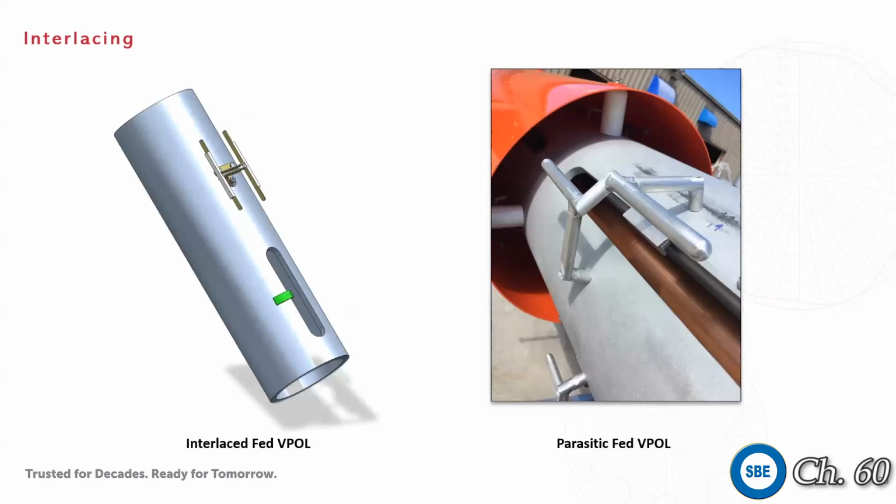Putting this into a more practical example, you can imagine walking towards an antenna that has this interlaced design. You're passing constantly through these different axial ratio combinations, which means that for someone who is holding a handheld that probably does not have the best antenna inside of it, reception is going to be all over the place. Worst case scenario, you're holding your phone and you turn it to go full screen and you just completely drop the signal and you lose your feed.